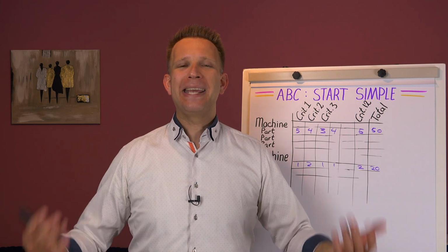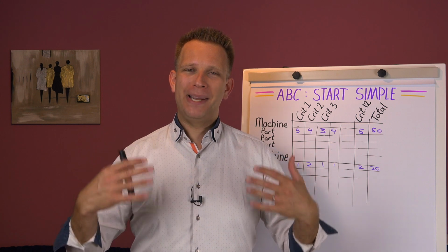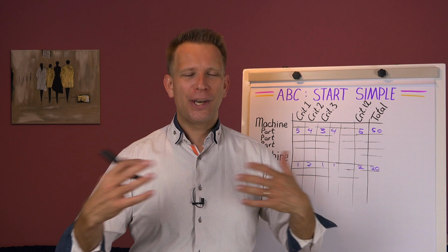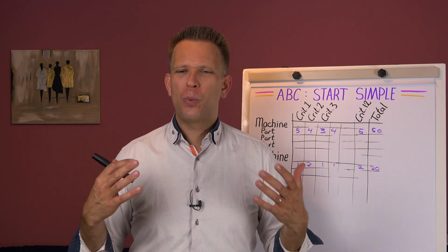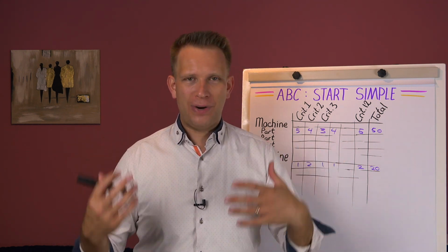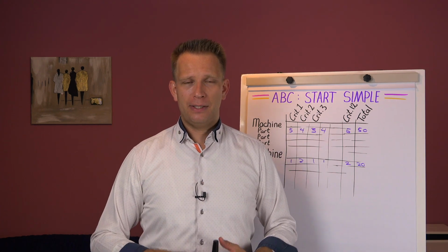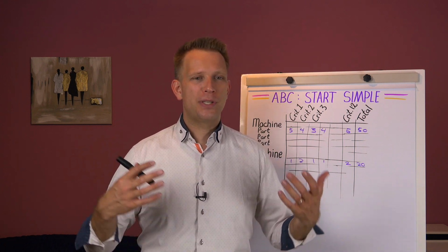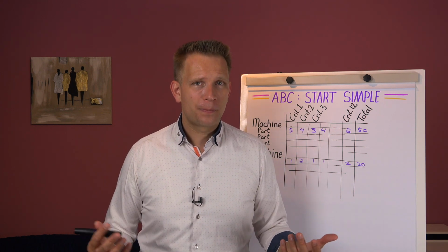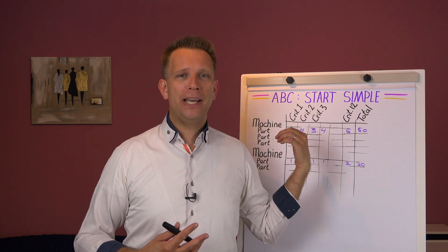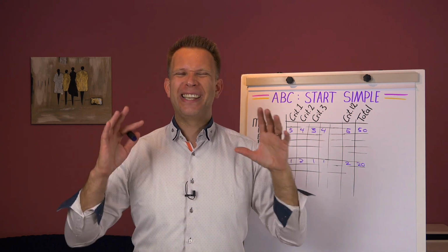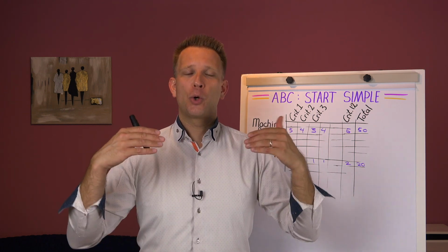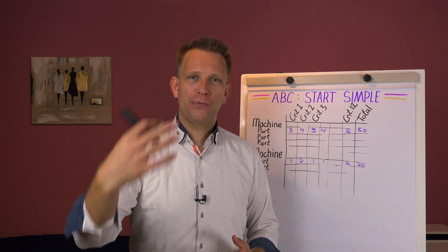Then you can always make it more complex when your maintenance organization becomes more mature, is more standardized, and can handle all kinds of different inputs. And also when your ratio of preventive to corrective maintenance becomes higher already. And so when you are still running a factory with loads of breakdowns and unplanned maintenance, you don't need a very strong ABC classification. You just need to get the highlights. So start there to make it quicker to get to action on those first improvements.